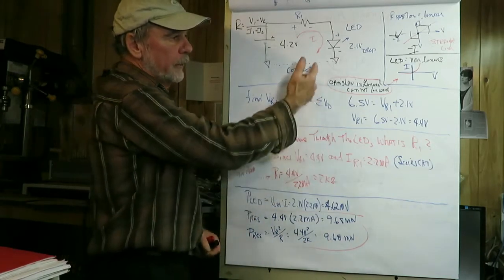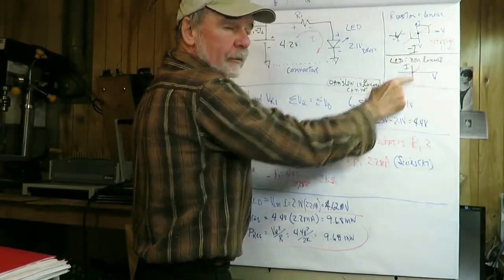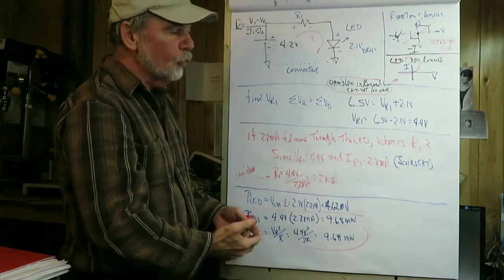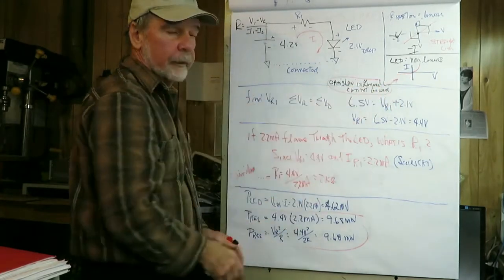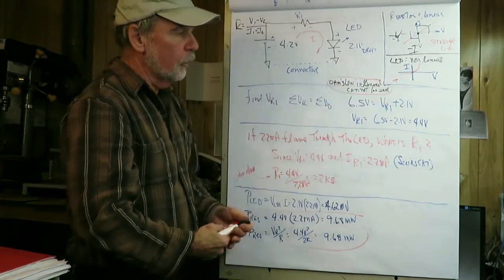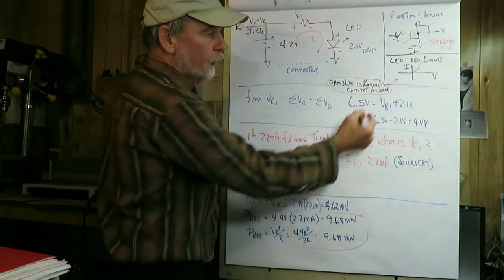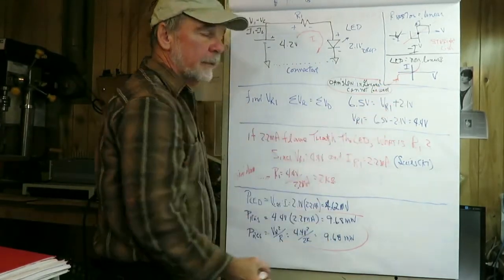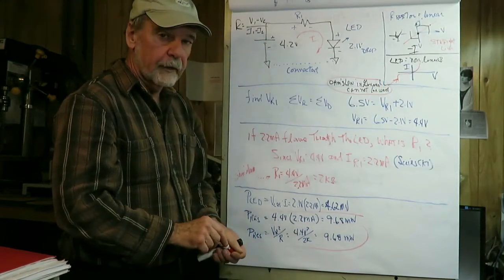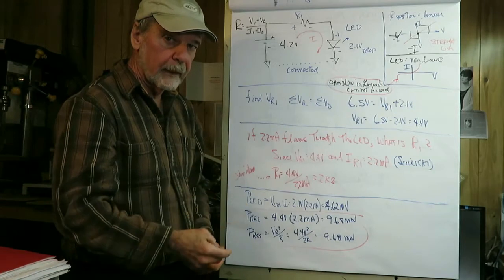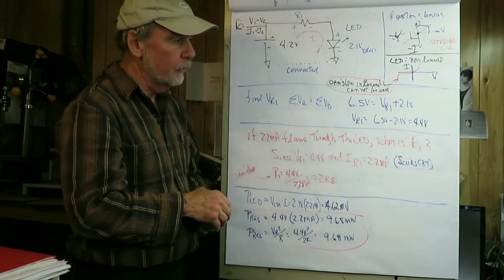Now, if we take a look at a light-emitting diode, it is anything but linear. In quadrant number 1, it's an exponential. So we can't really use Ohm's law in that sense. In quadrant 3, it's just basically the leakage current. It is very close to 0 until we exceed the breakdown voltage, which for a light-emitting diode is about 6 volts. And when it breaks down, things like that happen. Current rises in the negative direction with the negative voltage. The device overheats. High voltage, high current equals high power. Bang. So that's what happens if you break down a device.